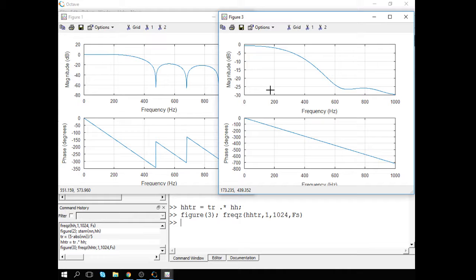Okay, so now we can control the cutoff frequency by Fc and the stop band attenuation with the window shape. The next trick, kind of the last trick we can possibly do here, is to do something for the transition bandwidth that we just messed around.